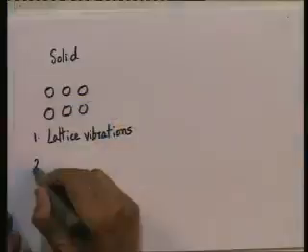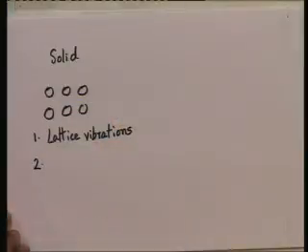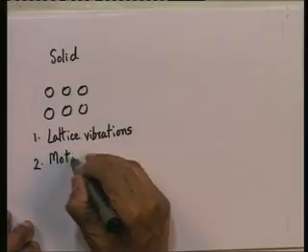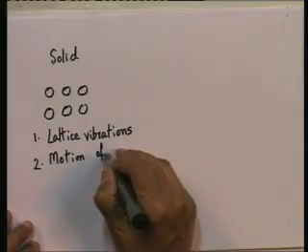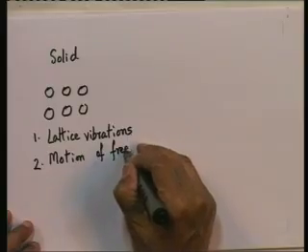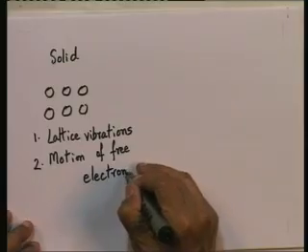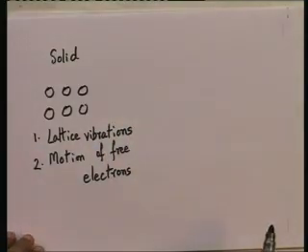So, the free electrons in a solid, when there is a temperature difference, also form the basis for transfer of heat by conduction. So, a second mode by which conduction takes place in a solid, if it is a metal, mind you, not in non-metals, there are no free electrons, is the motion of free electrons. These are the two modes, the second for metallic solids, the first for solids in general, non-metallic solids.